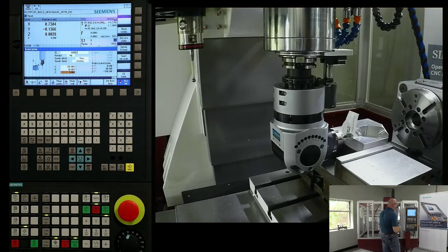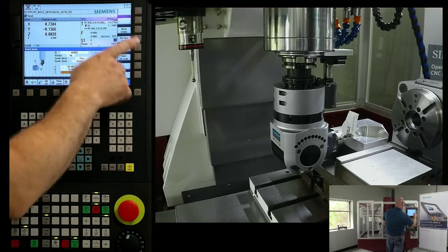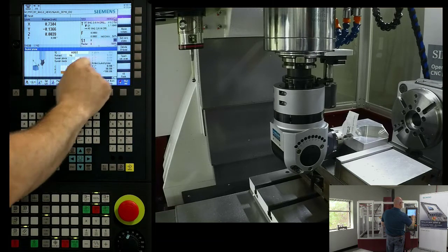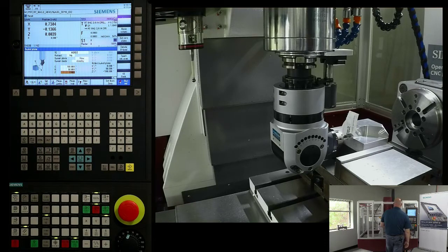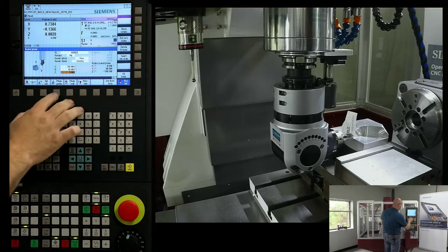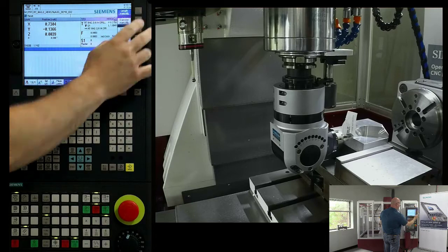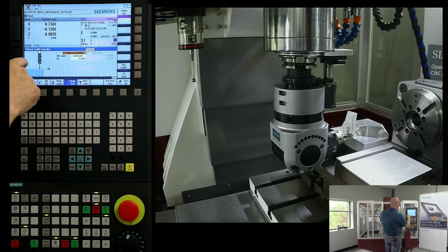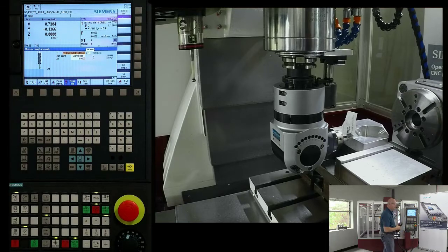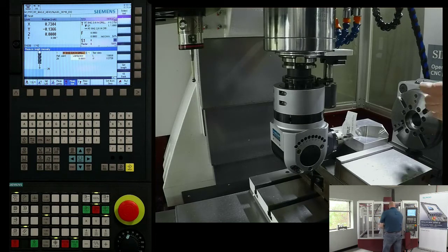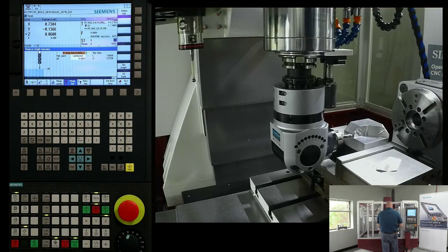All right, that's close enough. I just grabbed a little bit of the paper. Here I have an active tool offset, and we see I'm within a few thou, certainly, of that. It could be the difference of me pushing on the paper a little bit. But I can go in, measure my tool offset, set a length manual, and now it would update that offset to the appropriate position. So I can, for all intents and purposes, set my tool offsets at any orientation angle, as long as I use the swivel cycle here in jog to manage that orientation. At this point, we could certainly then start to move the machine relative to that coordinate system.